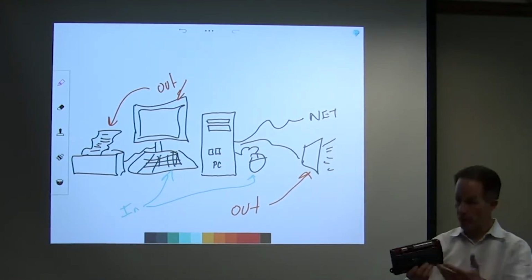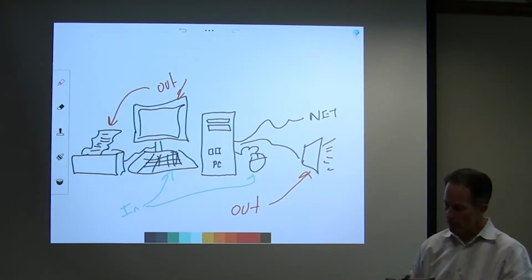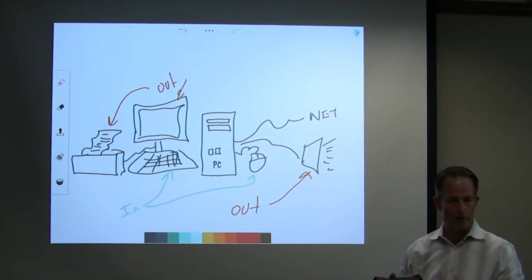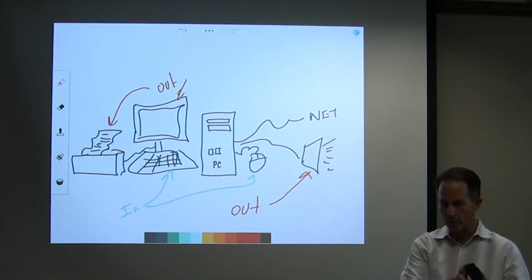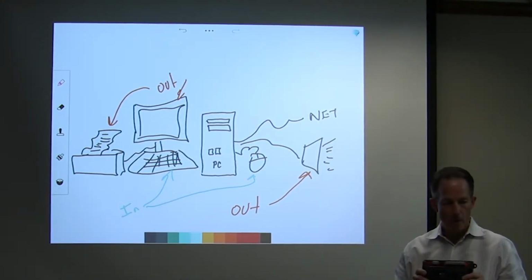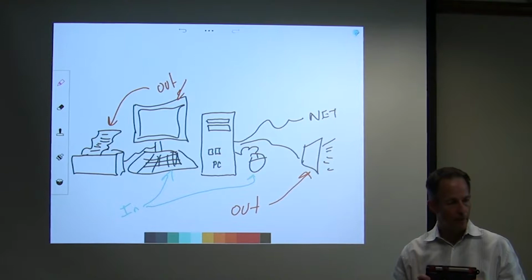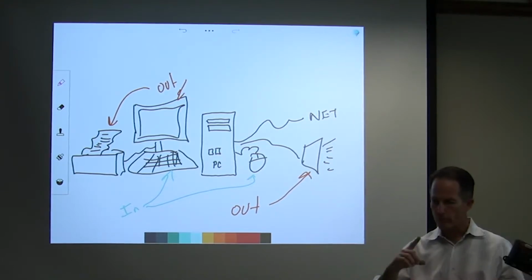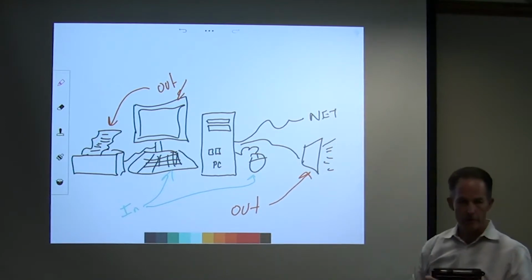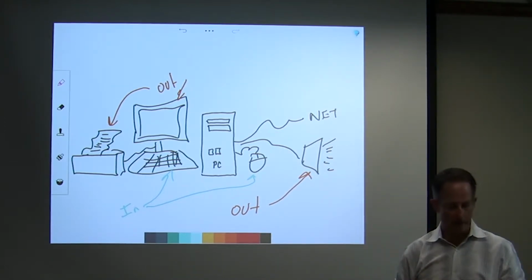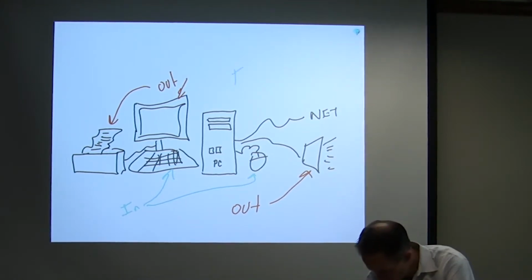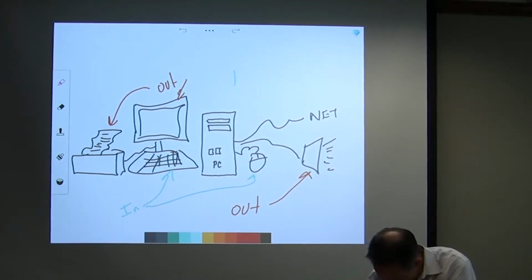There are some that are universal, configurable. Some of these have jumpers that you can change from different styles, allowing us to hook a resistor or a thermistor up to it versus a 4 to 20 milliamp signal. We also have network variables that we send back and forth, or network information through our Ethernet or other network communication. And those are a lot like doing email.